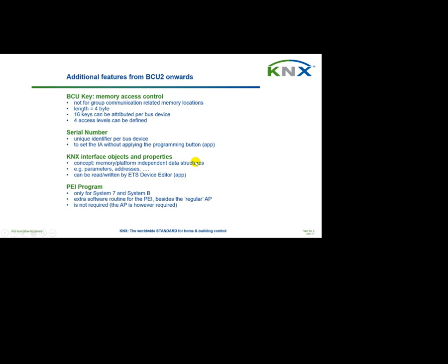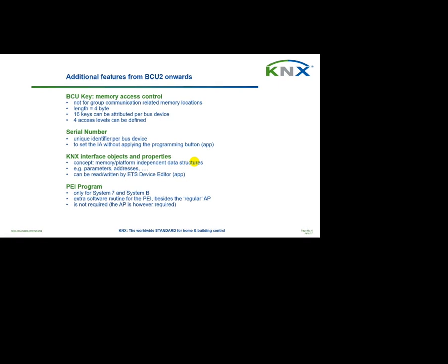Again, it's just to protect the device against programming from maybe another ETS. So if you protect it with your ETS, with your project, with this BCU key, then someone else cannot do that unless that person knows the BCU key. But as such, it is a protection against overwriting memory.